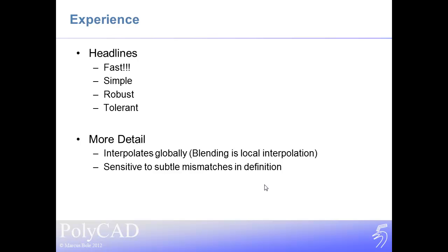Because we're now lofting from different directions, and unlike the blending approach which tries to average everything together, if there are mismatches between curves, these are highlighted quite well. Either the curve will vary in its location across the screen quite violently, or if it's not visible, we'll start to see discrepancies in the curvature. And as highlighted in that previous example, automating it does somehow start to limit the performance of it. It's not like a surface where it will fill everything in. If there's a gap in an edge, or there's not enough information in a particular area of the surface, this technique is not very good at estimating the shape of it. That really comes in when the blending method is used.